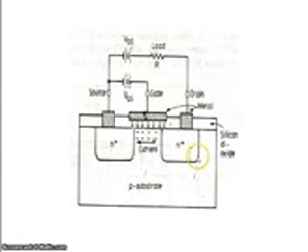Now when the gate is made positive with respect to the source, an electric field is established as shown in this figure. Here this indicates the electric field. Eventually negative charges are induced in the P substrate.